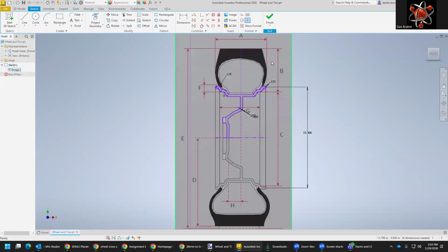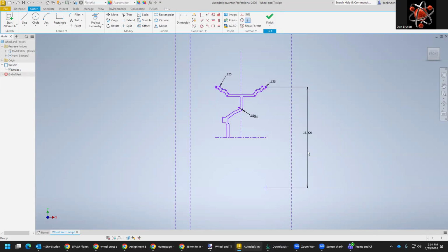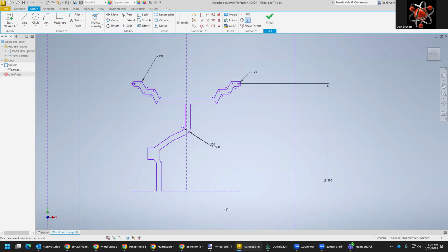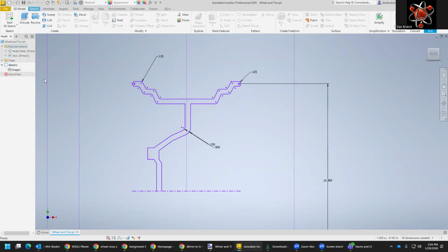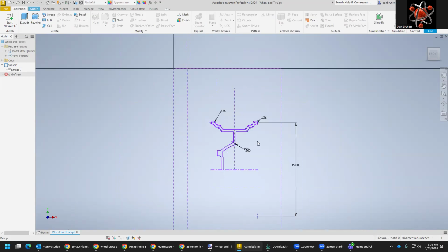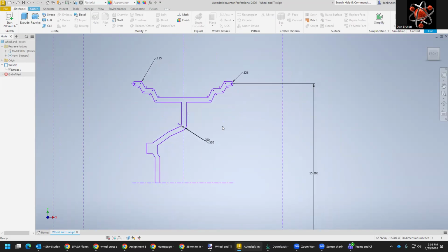I might want to just keep it in there for later. Can we do something like make it invisible? Let's try that. Okay, that's just in case we need it again. Now, do we have enough information here to perform a revolve and make a wheel? Let's find out. So if we didn't close any of those sections, then this is just not going to work. So we might have to go back and look at every little closed section there, unless there's a tool we can find to make it easier to find those discontinuities.